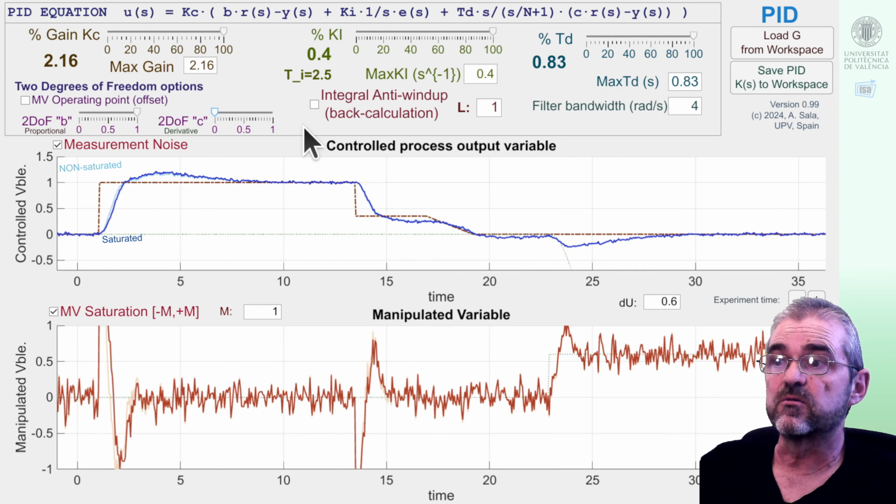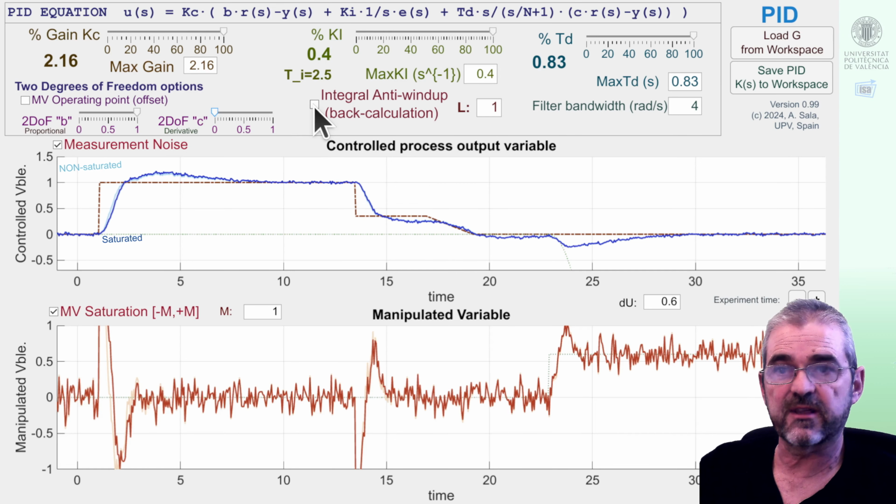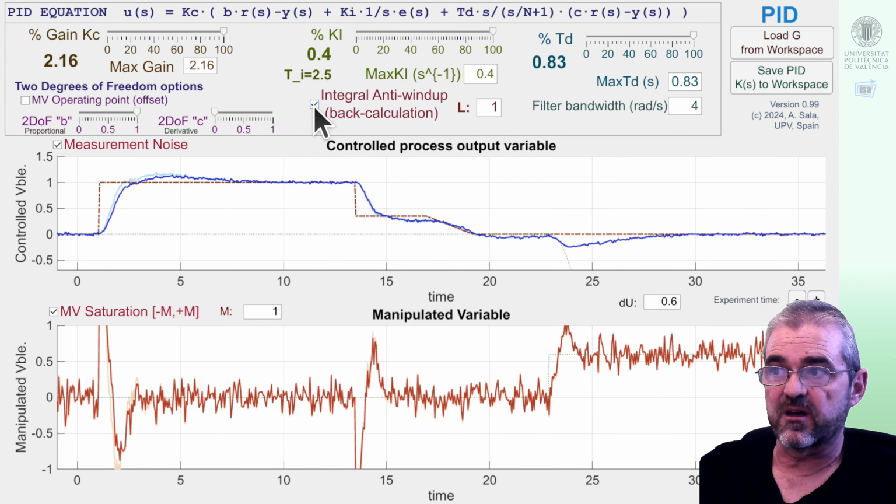And again, also if because of saturation I accumulate too much error, I need to apply the so-called anti-windup, so my final dark blue response will be the practical implementation with this output derivative, anti-windup and noise filtering that will possibly make it work in a realistic setup.